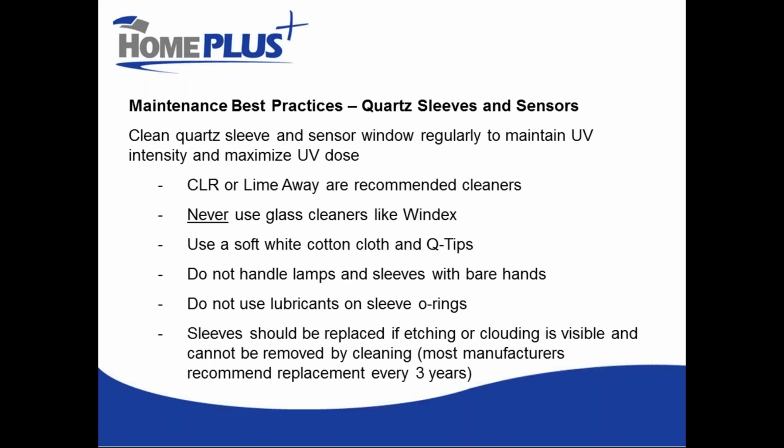So, best practices. The most important thing you can do for your UV system, other than ensuring that all of your pre-treatment equipment is operating correctly, so if you have iron filters or water softeners, that those are all kept operating properly, is to ensure that your quartz sleeve and your UV sensor window are cleaned regularly. And this will be a function, as I said earlier, of your own water conditions.